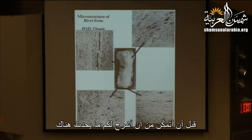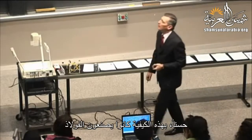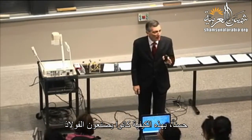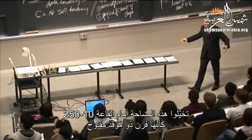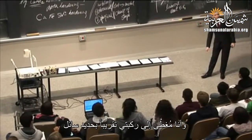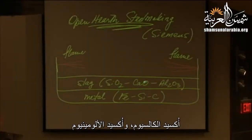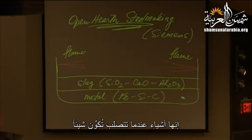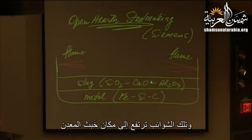Before I can explain to you what's going on there, I have to show you how they made steel. Imagine this area at the front of the room as an open hearth furnace, and I'm up to about my knees in liquid iron. On top of the liquid iron is a slag made of silica, calcium, and alumina. When it solidifies, it makes something not too different from window glass. But we use it for refining to get some of the impurities out of the metal, and those impurities go up into the slag phase.